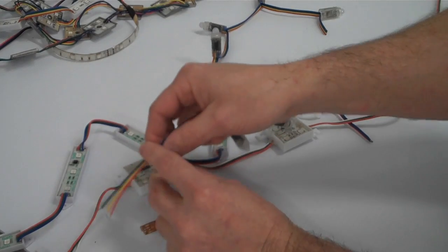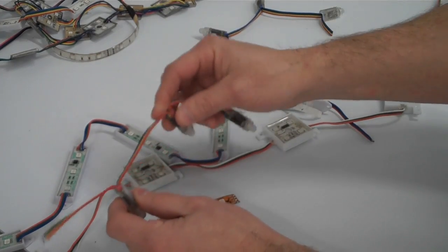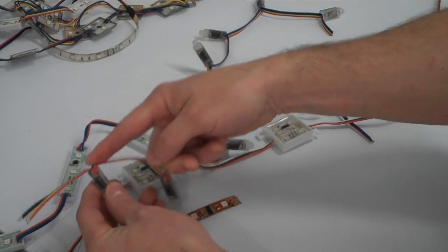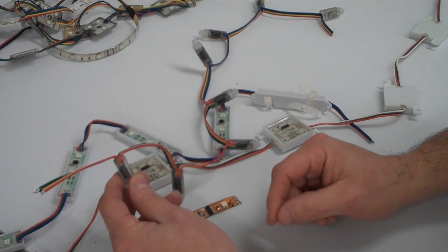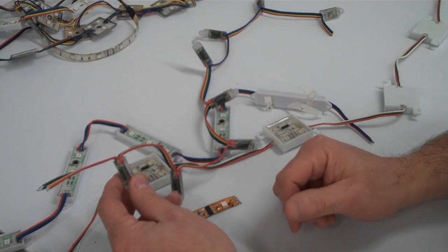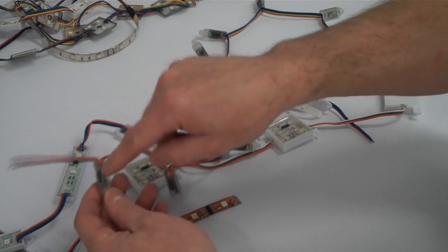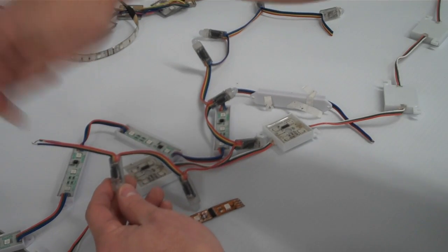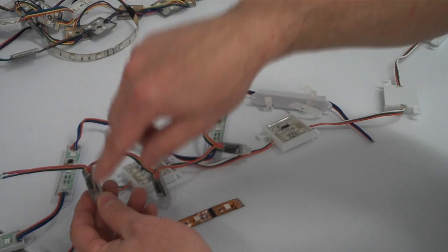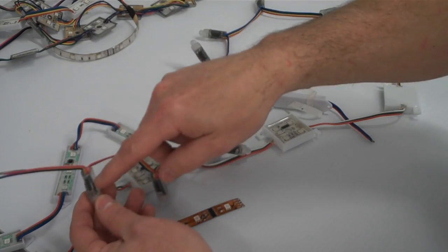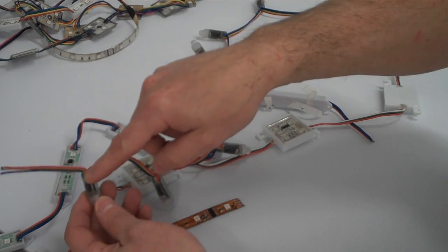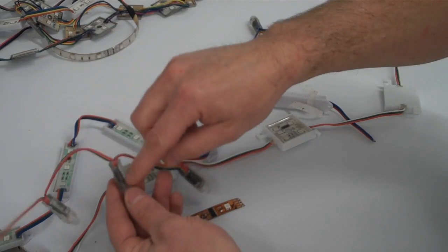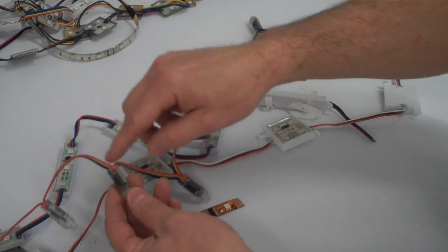Now, there's physical pixels and their addressing, so this is 1, 2, 3. But again, you may have logical addressing that is applied inside the controller itself. So in your controller, you're going to tell it that pixel 1, physically hooked up to this particular controller, is DMX or LOR channel 100, 101, 102. Again, RGB, we've got 3 channels. And then this becomes 103, 104, 105.